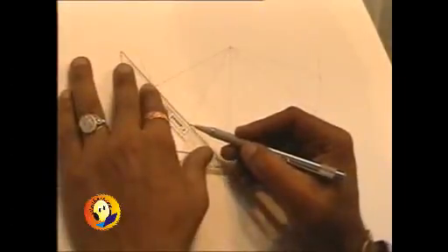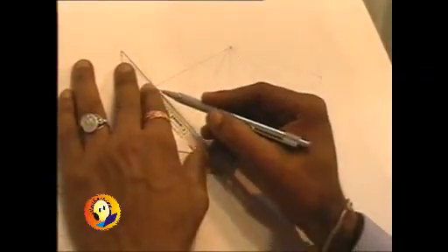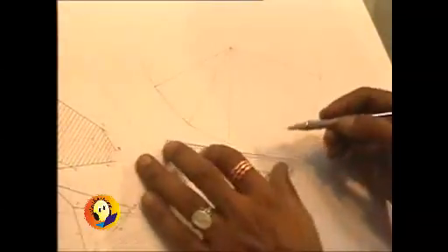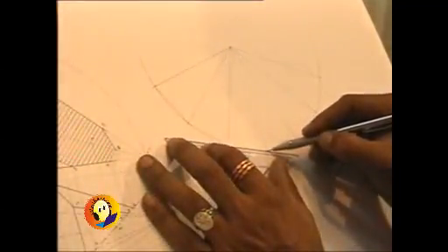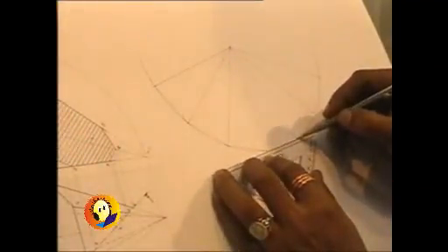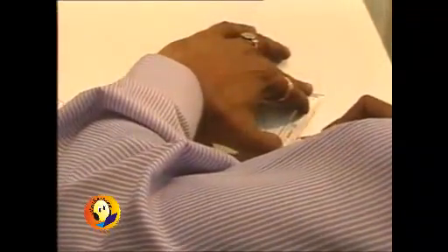And then even the bases of these triangles are to be shown. Generally the development that we are going to draw should not be drawn in 2 parts, and hence here we will have some basic condition as to from where we are going to open this particular hexagonal pyramid.